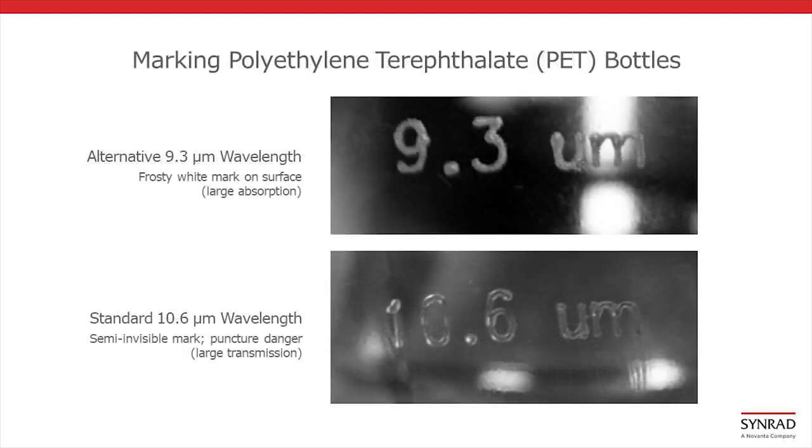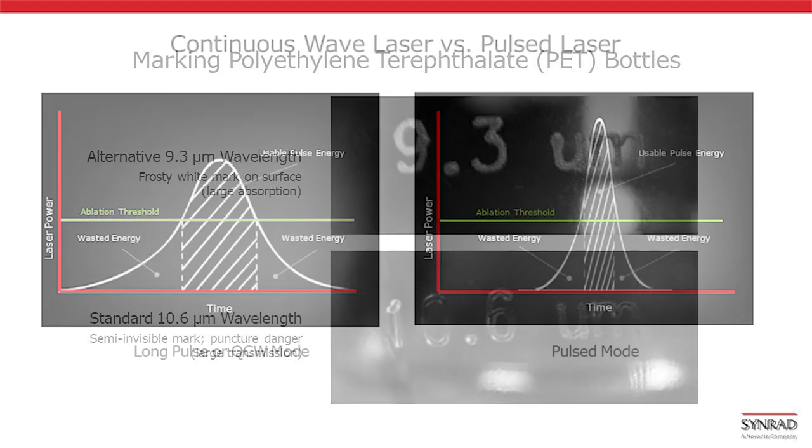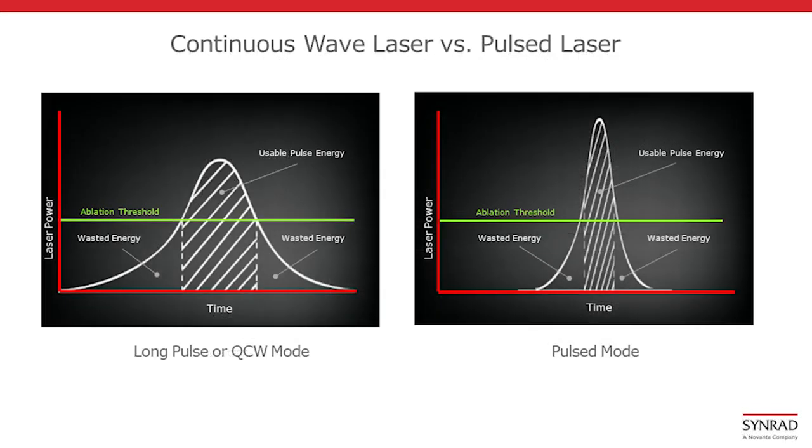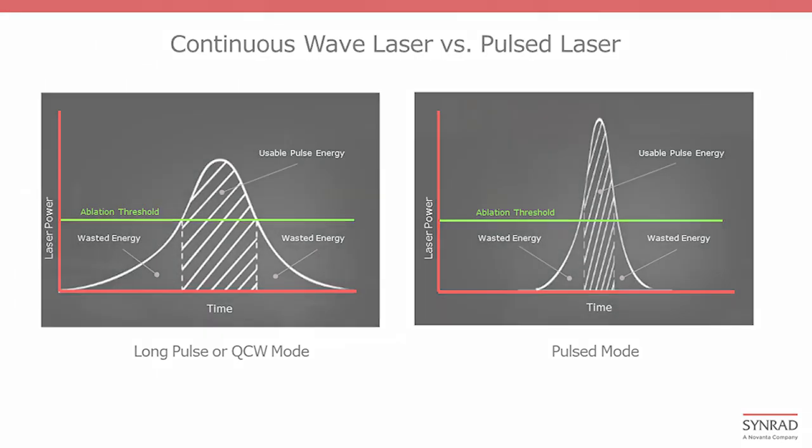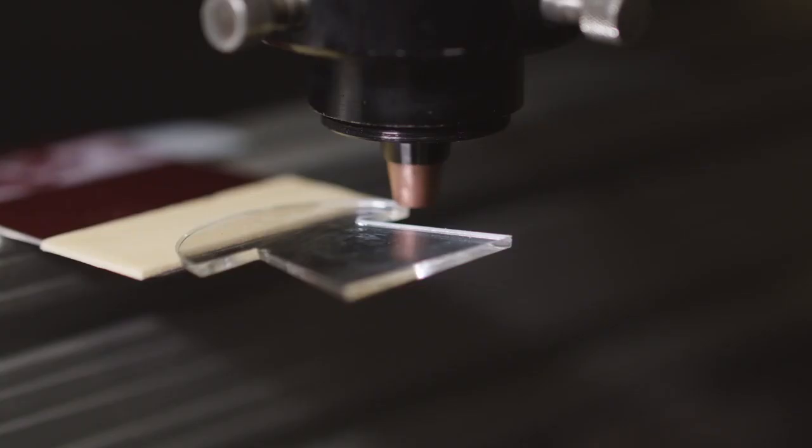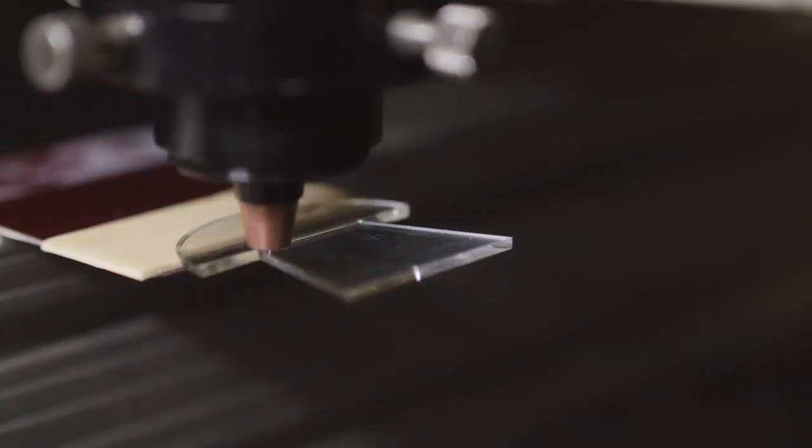Finally, the laser can be either pulsed or continuous wave. Pulsed lasers produce a series of pulses at high peak power. This delivers energy more efficiently and can reduce heat affected zone, penetrate thin materials more quickly, or pierce challenging materials like metals. In contrast, continuous wave, or CW lasers, can emit a continuous beam of light. These lasers are useful for marking, engraving, and creating smooth cut edges on materials like acrylic.